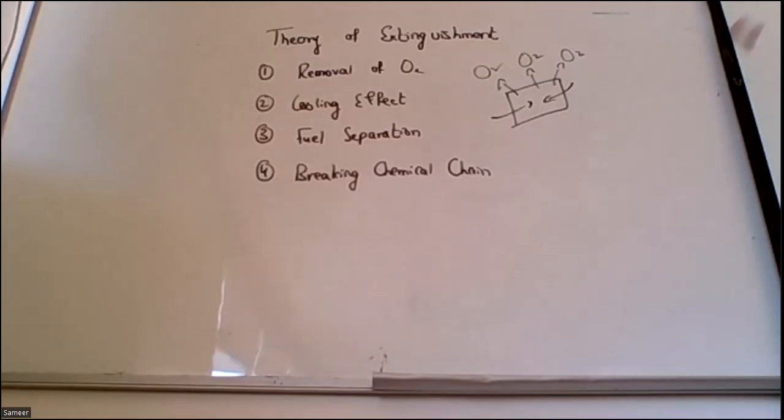We will discuss slowly and gradually. We'll move on towards human factors, NFPA 101: what type of opening should be there, what should be the width of the corridor, how many people should be there, how you will calculate each exit floor capacity. Based on that, NFPA 101 has some very strict regulations and standards so that all fire propagation and fire extinguishment methods become easier.